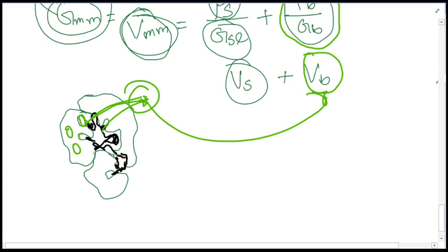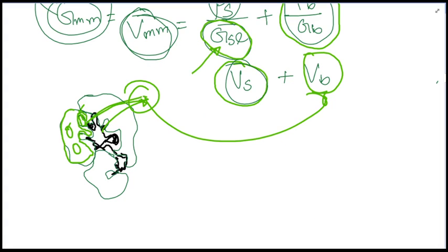These aggregates, it doesn't matter whether it is fine or coarse aggregate, but throughout this total aggregates we will be using it as the total volume of S, and this permeable and impermeable pores excluding the absorbed bituminous volume, the total volume has been used for the specific gravity. That specific gravity is called the effective specific gravity. That's why it is used and shown there.